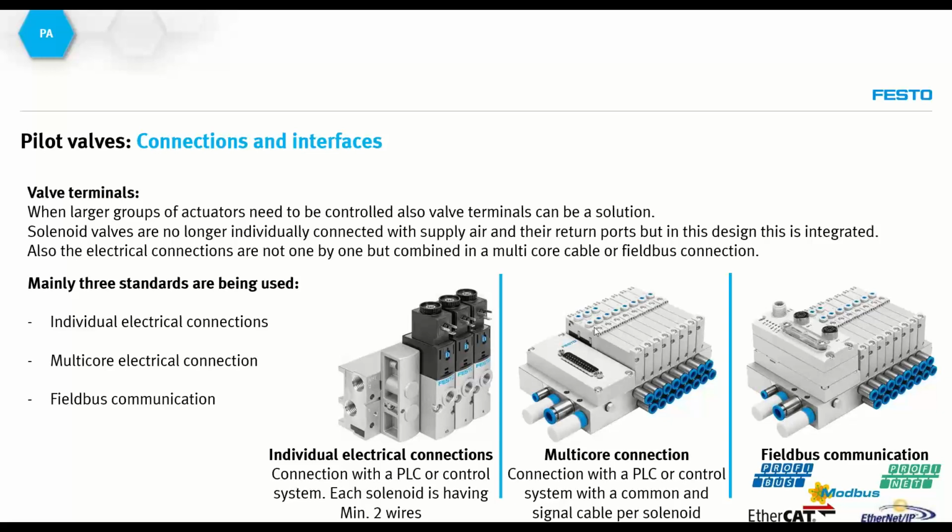So on this part where there are two blue buttons, this can be a 5x2 bistable valve, or there might be the use of 2 times a 3x2 valve within one housing. This means that more compactness can be achieved by building and using such a valve terminal.